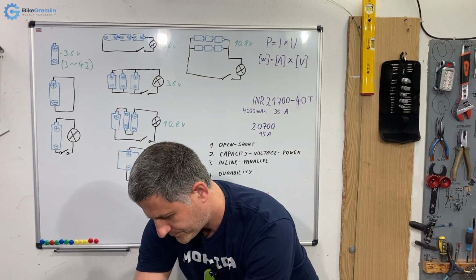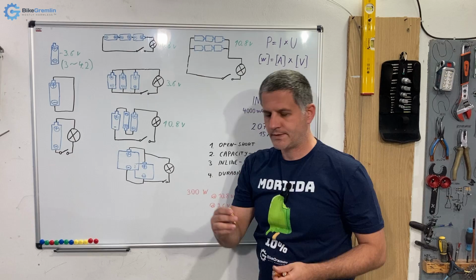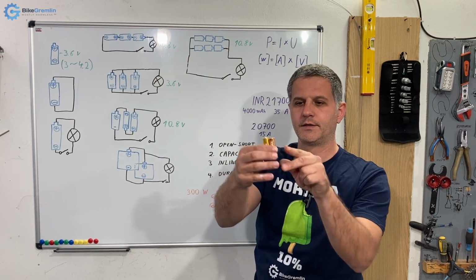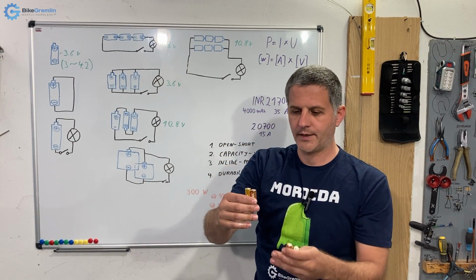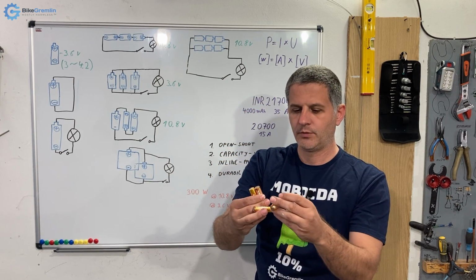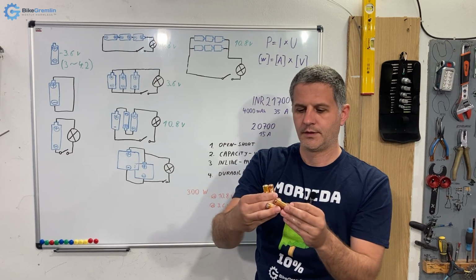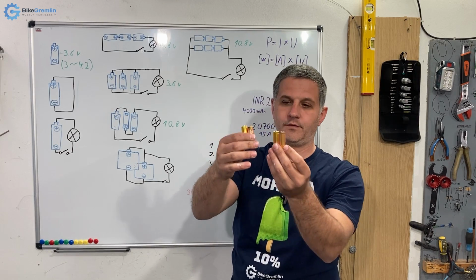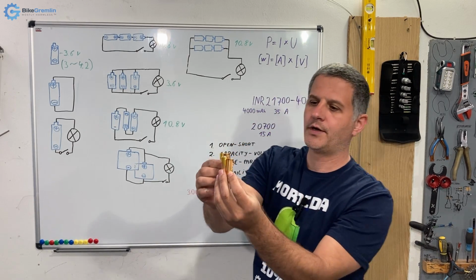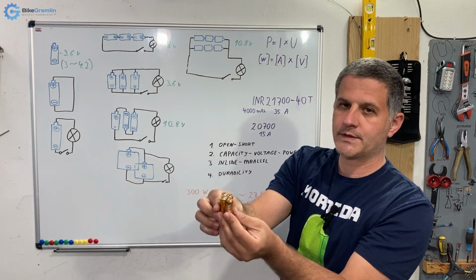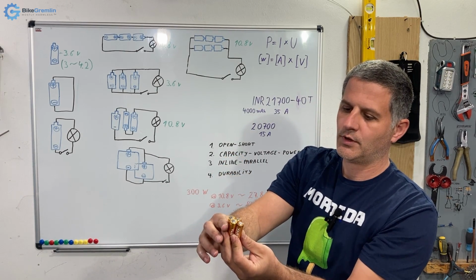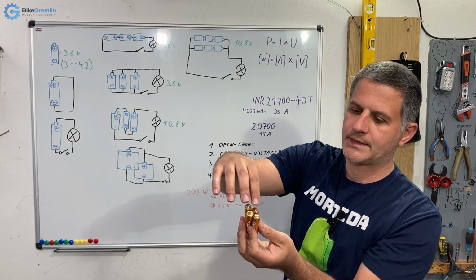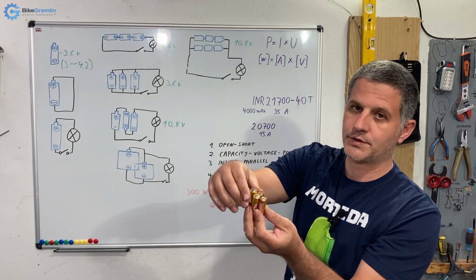So to try to visualize it better, let's say I'm only using 2 batteries in line. So I have this, and now I want to make it smaller, and I want to make another one in parallel. That way I will be using also the same principle. So now I got 2 packs of batteries that are in line, and I can connect them, stack them like this, for example, and just make sure to have the proper connection so that both plus sides and both minus sides are together and not short-circuited.